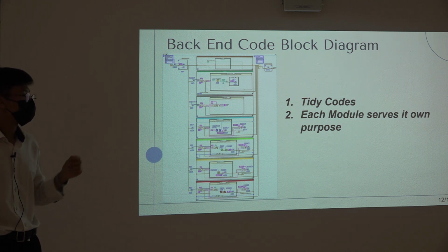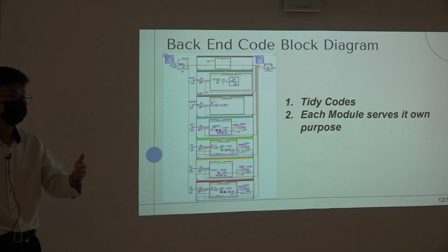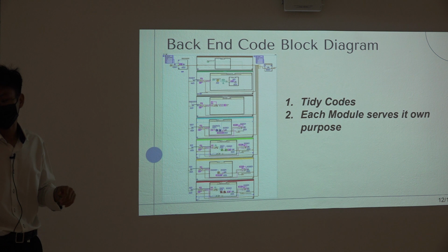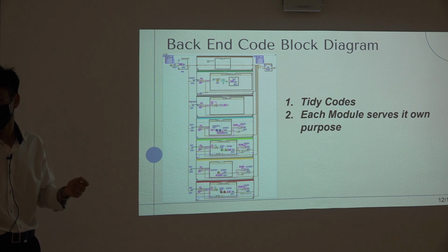Also, I understand that hardware devices might come loose if you don't touch them often. So I've implemented a re-establishing and reinitializing process in the loops, so that in any instance where the device is a bit loose, it will try to reconfigure itself to make sure that the system continues running and does not just die outside in the standalone. If not, an engineer will need to go to the system and make sure everything is connected smoothly.